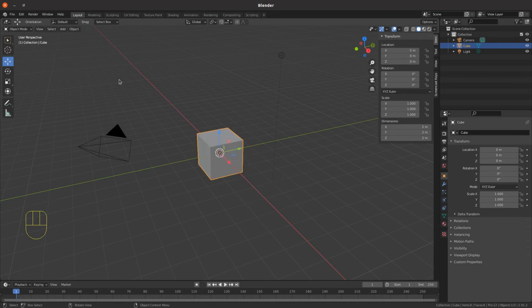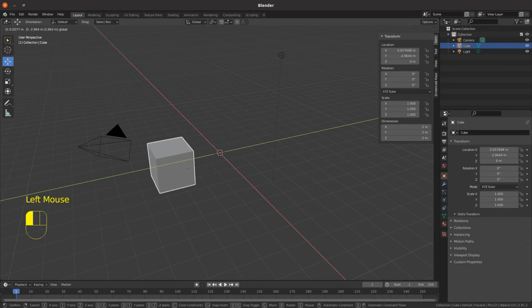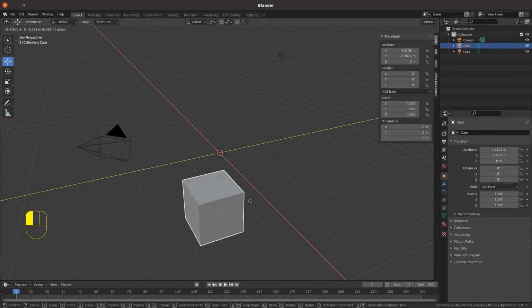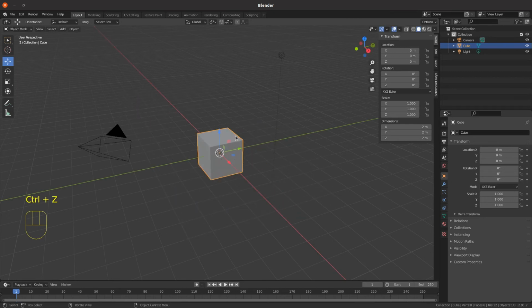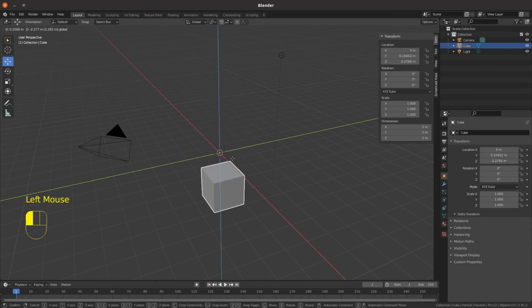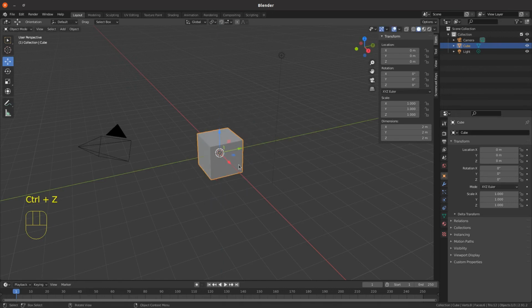And the same as we moved on a floor plane, you've got the option with the blue square handles. You work on the floor plane opposite to the colour of that one. So the Z plane means you're moving on the X and Y only, the floor plane, by grabbing the small square. And the same goes with if you grab the X, you can only move on the Y and Z axis. So that's the move widget.